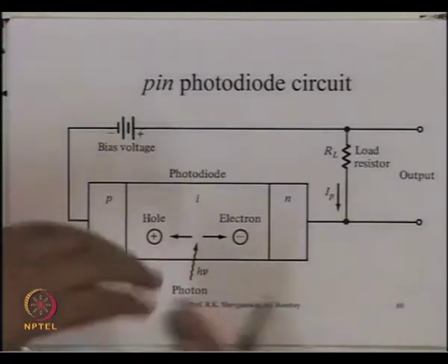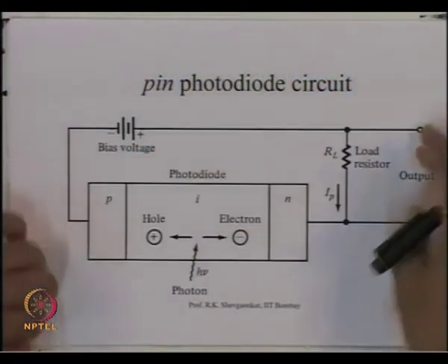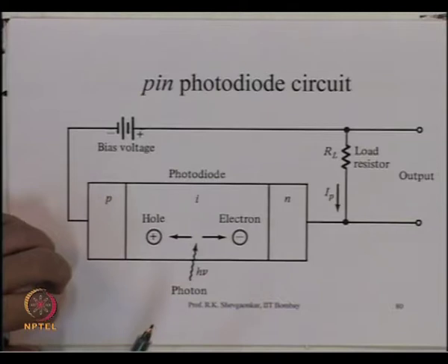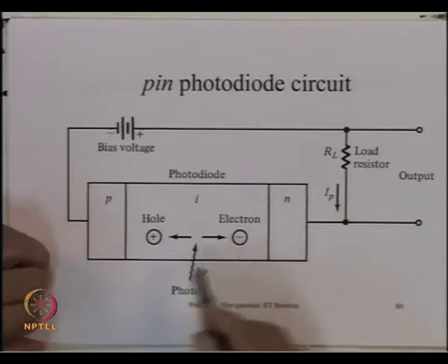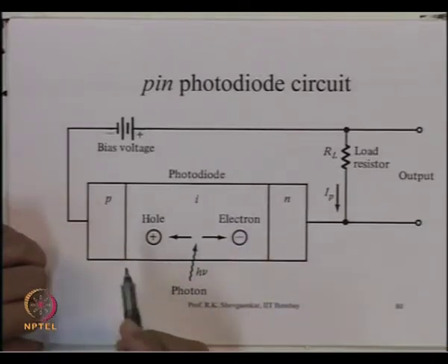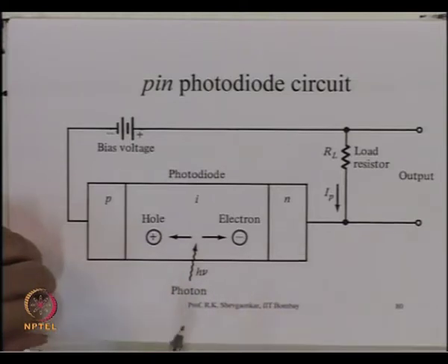Incidentally, it so happens that the circuitry which you require after the detector is invariably not current controlled, but voltage controlled. So essentially you have to convert this photocurrent into the corresponding voltage, and that's what we do by passing this current through a resistance, called the load resistance, and this voltage is proportional to the photon flux which is incident on the device. So we have a proportionality between this output voltage and the optical power incident on this photodetector.